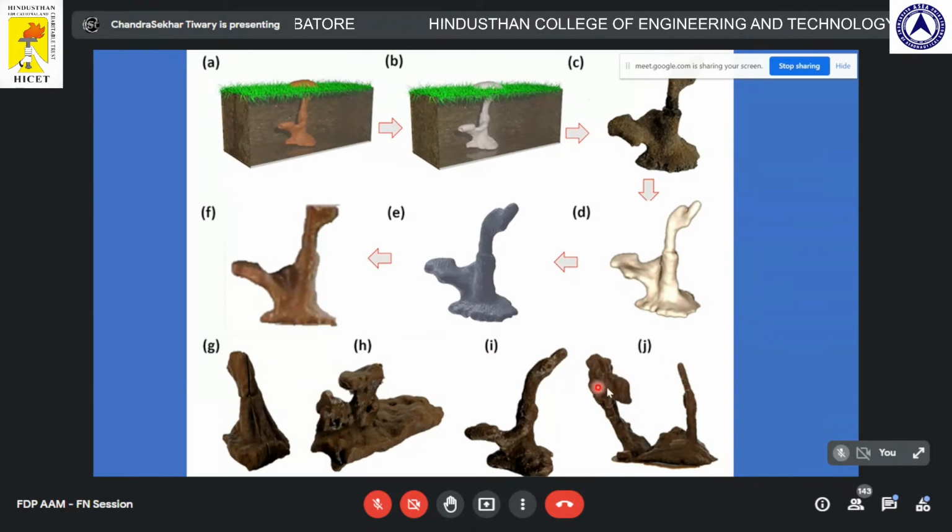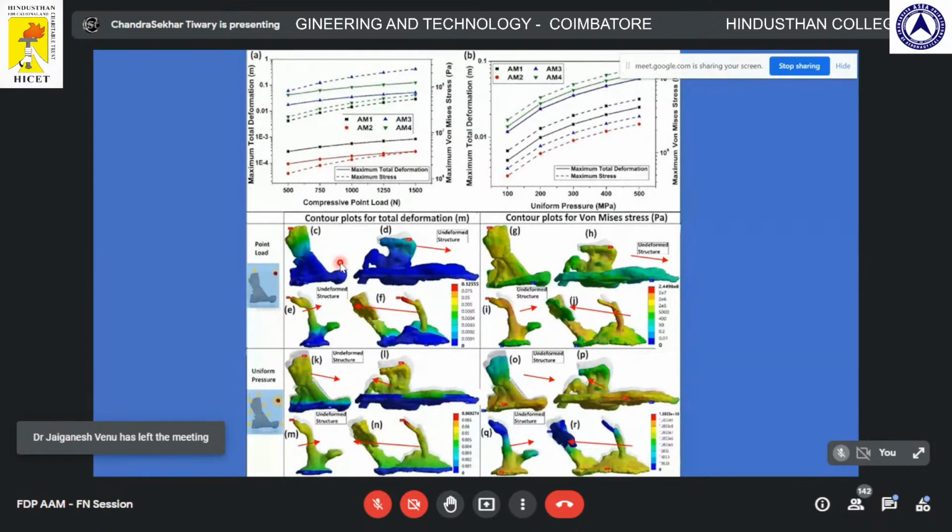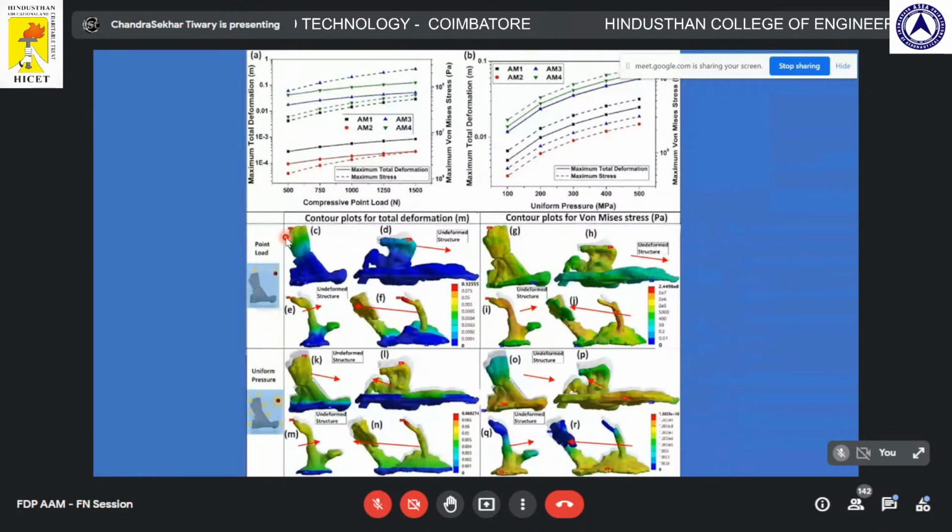And then we try to understand what really happens in terms of deformation. Again, the computer simulation comes into the picture because you have already built the model. You can easily do all sorts of deformation study. The first study is point load, assuming that someone puts a leg on top of their house, or something is moving around, it's going to press localized stress. So for that we do a point load analysis, and we apply load here and look at the stress distribution.